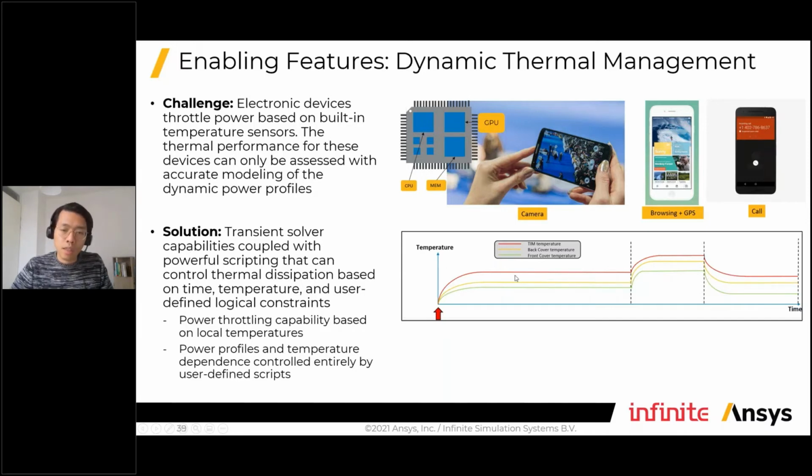And this kind of dynamic, or the entire load cycle, is crucial, because then we know that when we're trying to overshoot or turbo boost our performance, how much time can we do that? And if we cannot do that, how are we going to downgrade our operating frequency so that we can still perform reasonably well while we avoid any thermal issues?